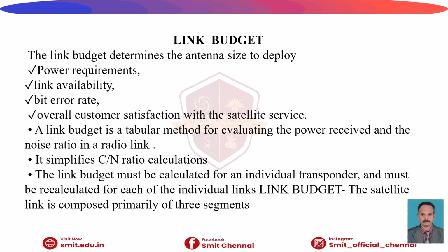If you go with the weight of the satellite, weight is very important because the launch cost depends on the weight. Larger satellites require larger launch vehicles. The fuel requirement also increases. The structural requirements become more complex. So for this we need to reduce the weight and optimize the power. Generally, a lighter satellite may carry a small antenna with larger power requirements.